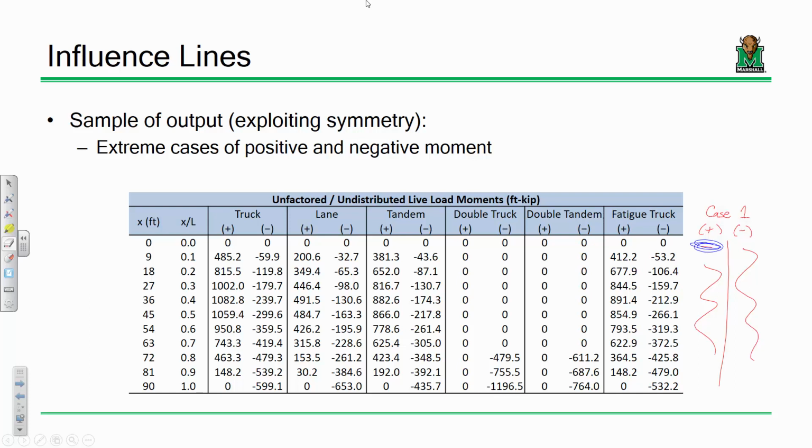Yes, exactly. See, influence lines are sort of an inverse of shear and moment diagrams, if you remember. When you're doing a shear and moment diagram, the loads sit still, but your plot is continuous across the entire span, right? When you do an influence line, your point of interest sits still, but the loads move, okay? So an influence line will allow you to determine the worst case position anywhere on the bridge, but its limit is that it will only give you the worst case scenario at that point.